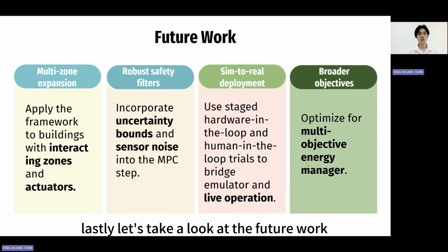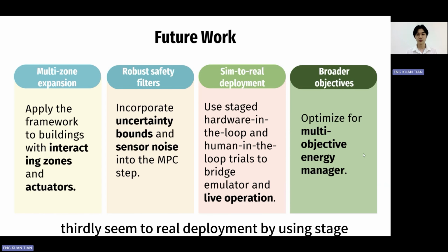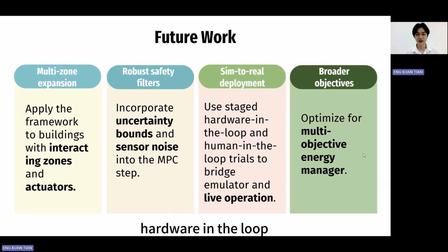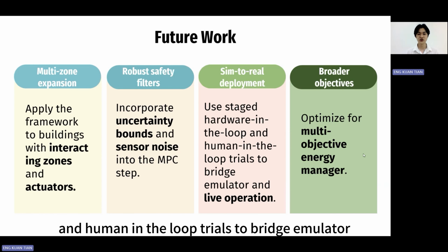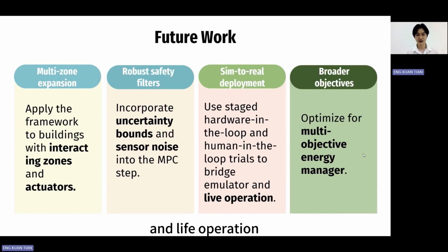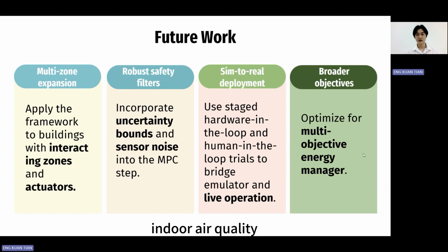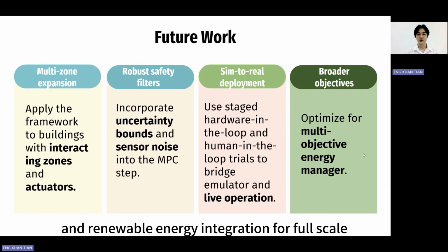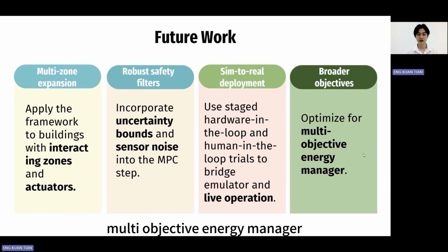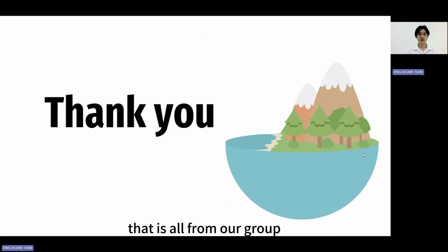Lastly, let's take a look at the future work. First, multi-zone expansion, by applying the framework to buildings with interacting zones and actuators. Next, robust safety filters, by incorporating uncertainty bounds and sensor noise into the MPC step. Thirdly, sim to real deployment, by using staged hardware-in-the-loop and human-in-the-loop trials to bridge emulator and live operation. And lastly, broader objectives, by optimizing humidity, indoor air quality, and renewable energy integration for a full-scale multi-objective energy manager. That is all from our group.